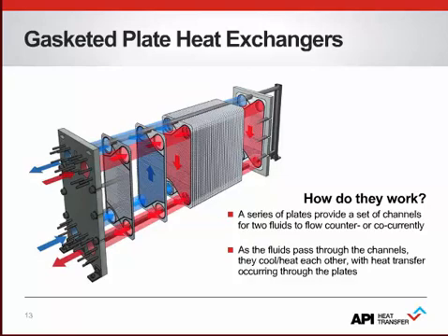The picture shows a so-called single pass unit with all connections at the front fixed head. There are also multi-pass units possible in order to extend the time the fluid is heated or cooled. In this case, you will find connections also on the movable cover of the plate heat exchanger.